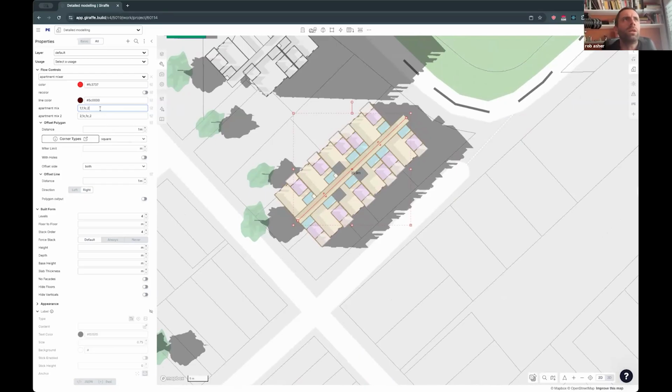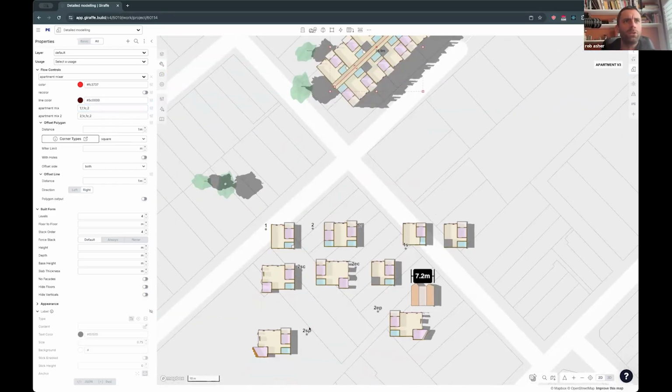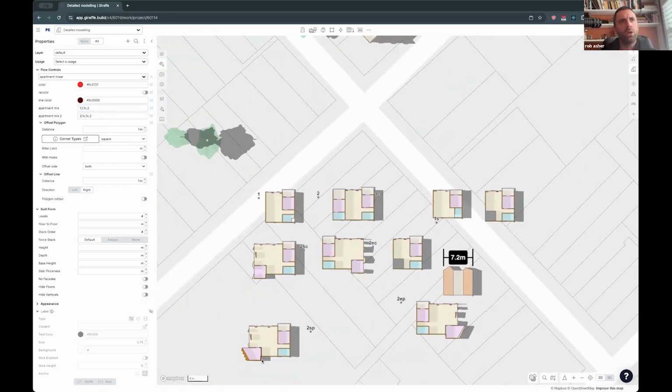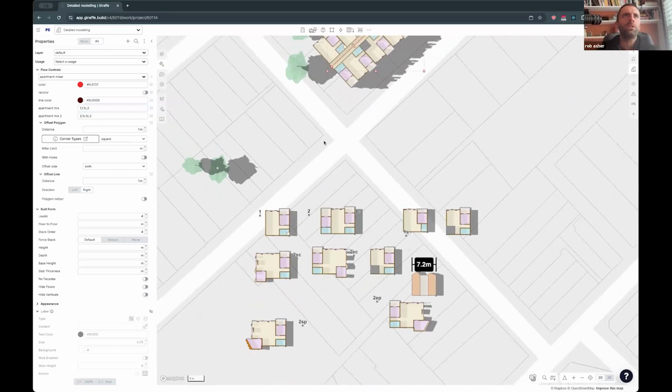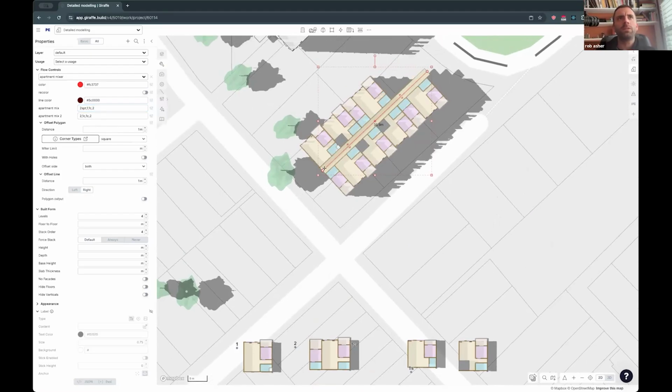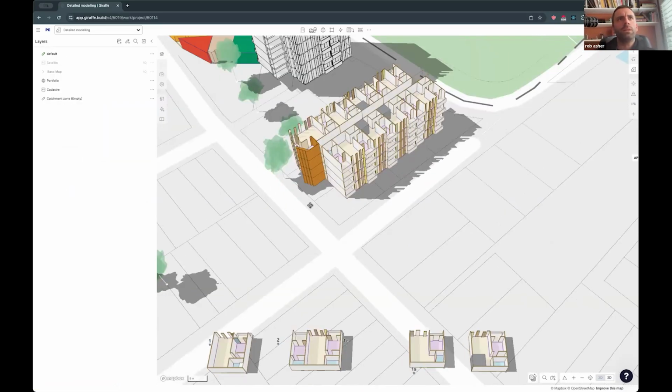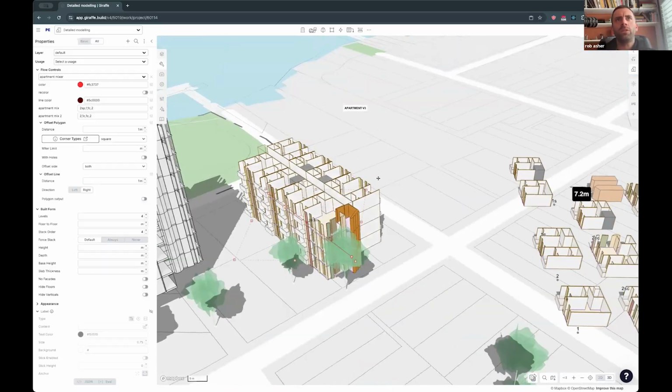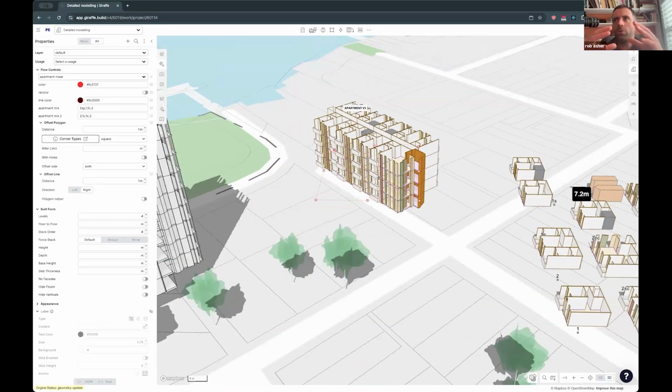Now, what's so nice about that is I've got a type called, you see this, 2SP. So that's a 2 at the start for the S, and then the P is this peak. So if I change that 1 to a 2SP, I get that 2SP hanging off the end of my corridor over there. And you can see this is a specific solution to a problem. It's not quite the internal corner problem, but it's the end cap problem.